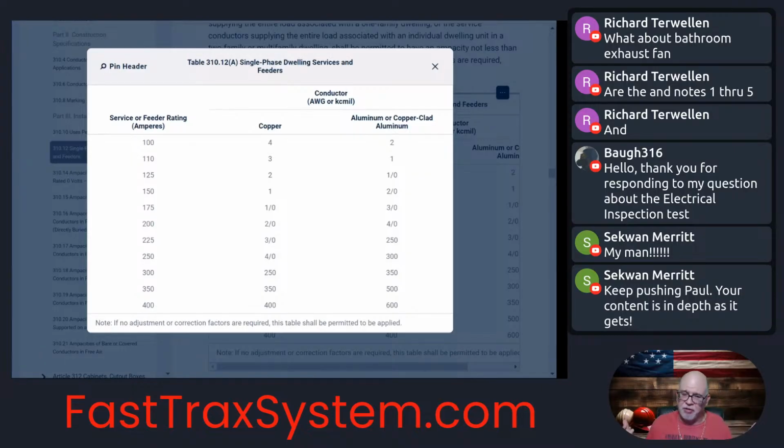And you're usually never going to have more than 3 current carrying conductors for a typical service, especially a residence. So that usually doesn't come into play. But the ambient could come into play, but ironically, I just don't see many people taking it into account, but you're supposed to. On an exam, it could come into play, so be aware of that.